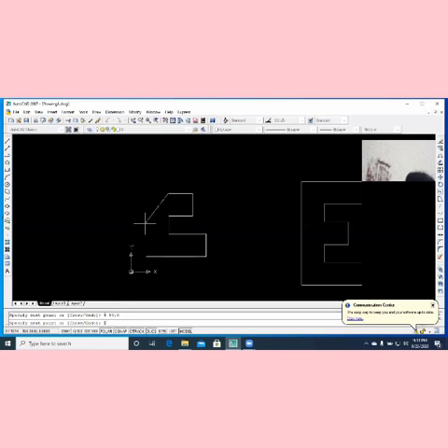Then Shift Alt 0, 60, you enter. Then Shift Alt 125, 0, you enter. Then Shift Alt 0, 75, you enter. Then Shift Alt minus 200, 0, you enter.